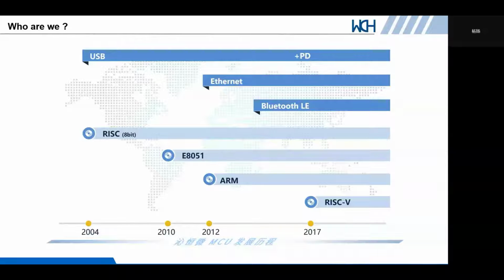By 2010, we had implemented a single-cycle design of indirect addressing instructions on the basis of the traditional 8051 core, and innovatively brought DMA into the 8051 architecture, and an enhanced version of the 8051 core was designed. RAM access has been reduced from 2 cycles to 1. The efficiency was improved by 50% based on this core.